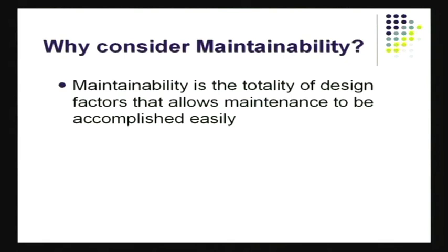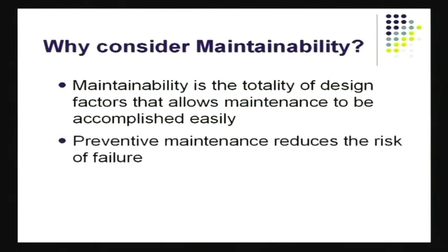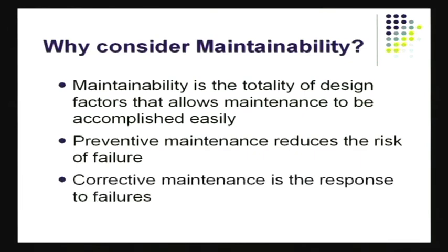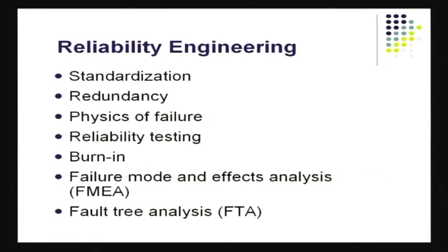Why consider maintainability? If you don't do that, the total cost of downtime is going to go up. And if you are not able to maintain the car, then you'll be doing less preventive maintenance, and it's going to raise the risk of failure. Corrective maintenance is actually done in response. After the failure has taken place, then you do corrective maintenance. This is something you should not have to get into.